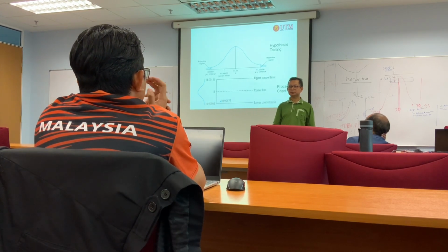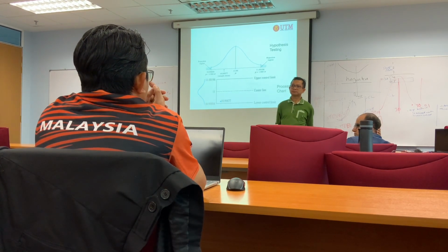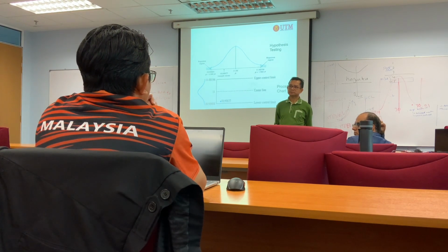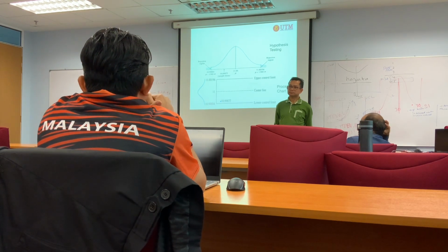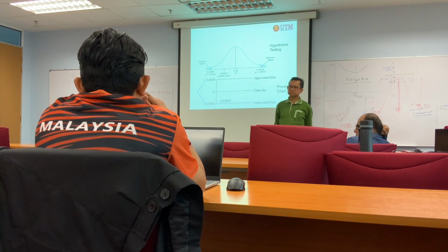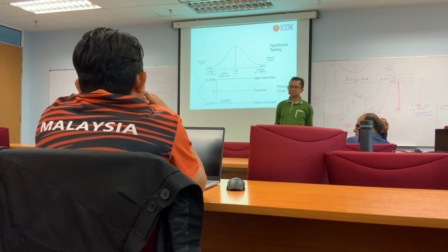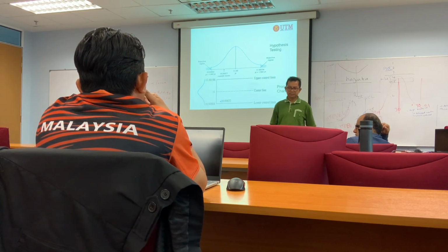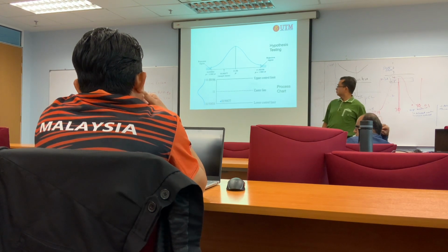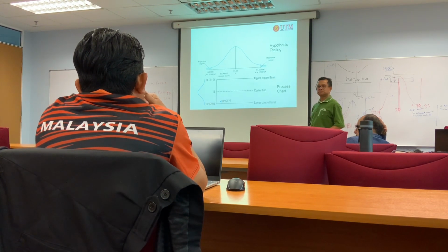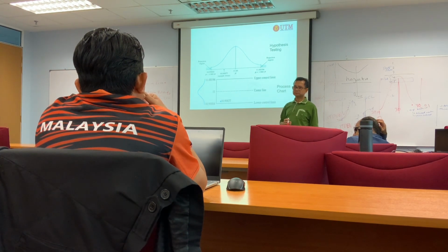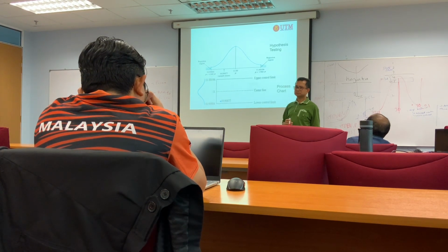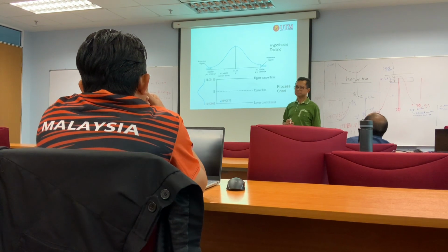How about, for example, quality parameters like pH, or conductivity of water? For example, we have the water analysis. So in the water analysis, there is turbidity, for example. So at the center is actually the targeted value, the standard value. Yeah, for example, turbidity, 30 NTU, right? So we monitor this. So for example, suddenly the NTU is at the upper limit or on the upper border, but it's consistent. So actually we say okay, our equipment is reliable because it is giving consistent values, but only the value. But we can check the accuracy, we calibrate.